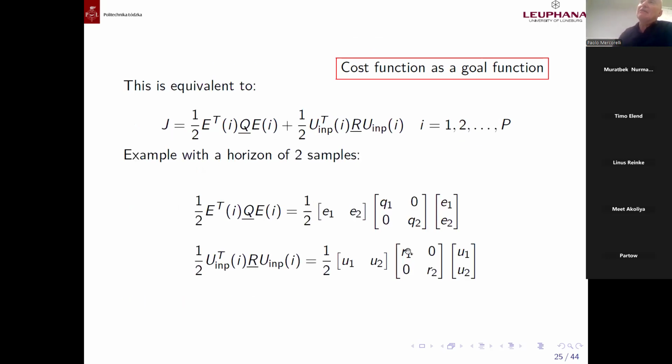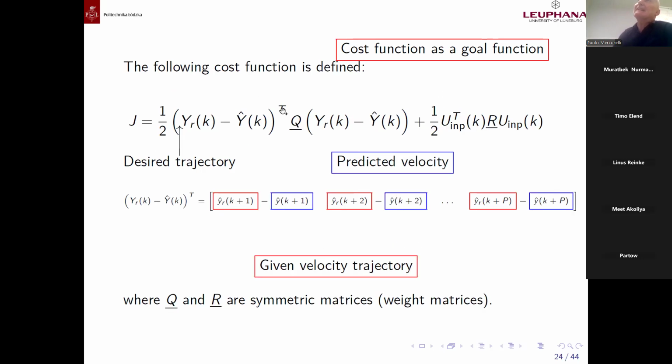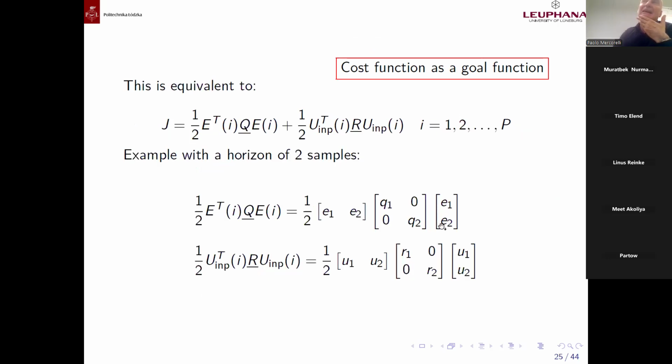And the same concept applies between R1 and R2. Here I clarified a little the relation between Q and R, which means between the error and the U. Vice versa, in the same way, if I consider a larger Q, larger Q means I would like to minimize the error, almost neglecting what I have to spend to achieve this. The same can be considered between Q1 and Q2 and R1 and R2.